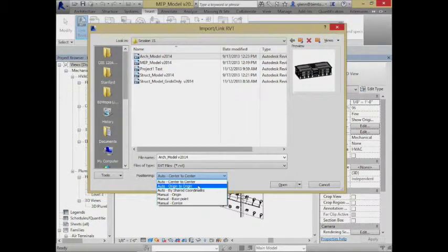Origin to origin says, if we all agreed and set up the same XYZ 0, 0, 0 point for that system, and we started all the files using the same origin, they will forever and always be linked at that same point. So it's a very cohesive way of tying things together. Origin to origin is always one of my favorite ways.